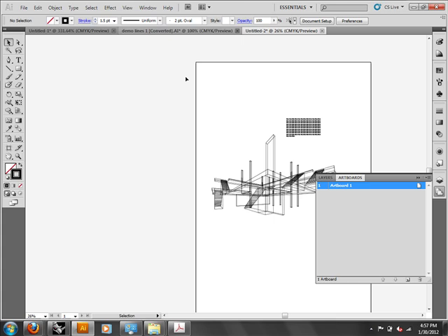In Illustrator, when you use the pen tool, I noticed whenever I try to do a line in one layer and then snap to another layer, it turns into that layer and kind of pieces. That's why you have to lock your layers if you're going to be adding any lines. So if I lock the layers, it can't add to a line if that layer's locked. Okay.